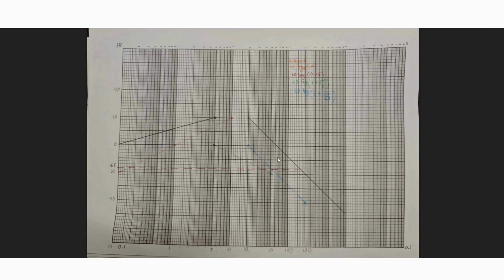And then at x-axis 20, we will have a slope that will be going down, and for the solid line, it will go down -40, because if you remember, in our original equation we have squared, so we bring the square in front of 20 and it will become 40. In this equation it will be -40 from our equation, so the last line will go down to -40 decibels.